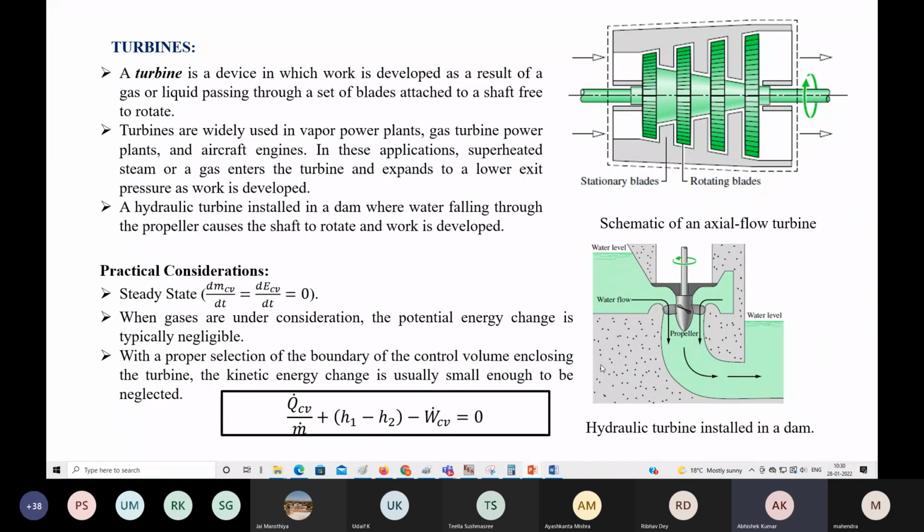Okay. So here, in case of a turbine, this could be any turbine. What is happening over here? The fluid is coming like this and the fluid is leaving like this. This is high enthalpy fluid in case of a steam turbine, or a gas turbine, high enthalpy fluid. Then here enthalpy loss is happening because it is expanding on the turbine blades. So this enthalpy loss itself is converting into our work. And then here low enthalpy fluid is coming.